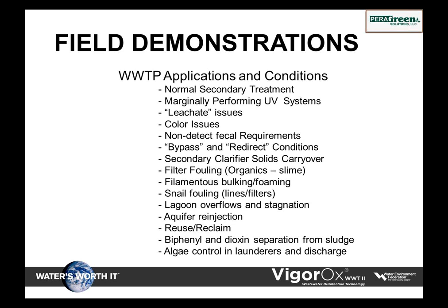Filter fouling. We're finding that this will take care of the organics and slime layers that build up in filters. You can also use it for filamentous bulking. We've seen that in troughs where you can reduce that. You could also put it in your recycle stream. Quite a few people use chlorine bleach right now for that.